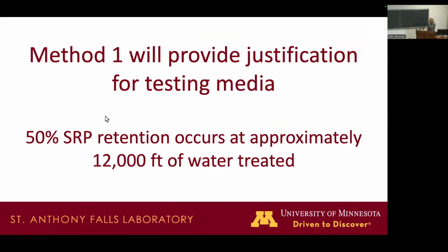So method one will provide a justification for testing the media. Roughly 50% phosphate, soluble reactive phosphorus, retention occurs at approximately 12,000 feet of water treated. That's basically what we found.